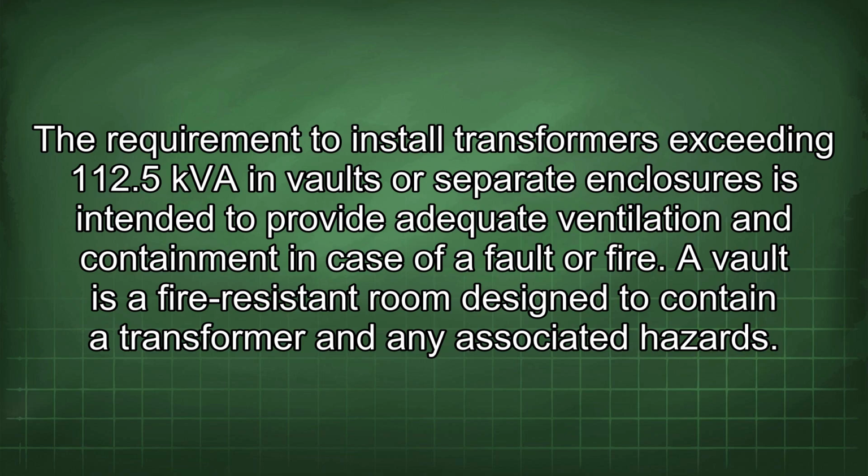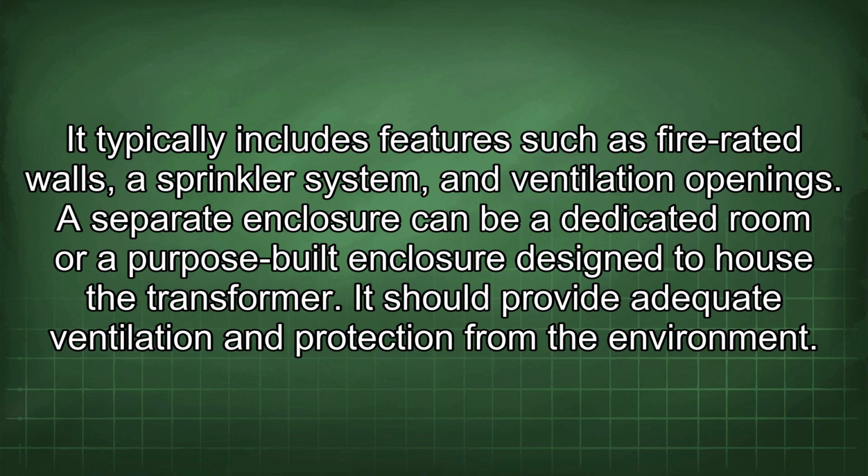A vault is a fire-resistant room designed to contain a transformer and any associated hazards. It typically includes features such as fire-rated walls, a sprinkler system, and ventilation openings. A separate enclosure can be a dedicated room or a purpose-built enclosure designed to house the transformer. It should provide adequate ventilation and protection from the environment.